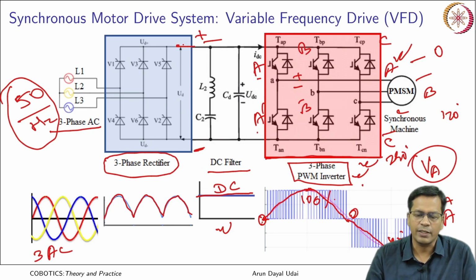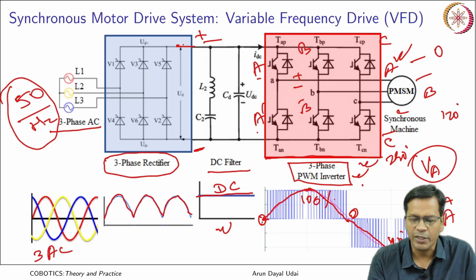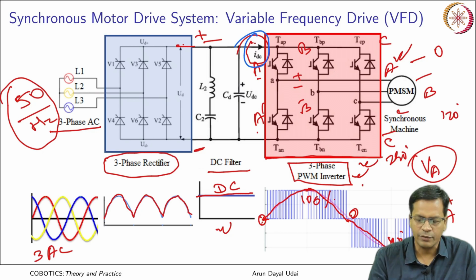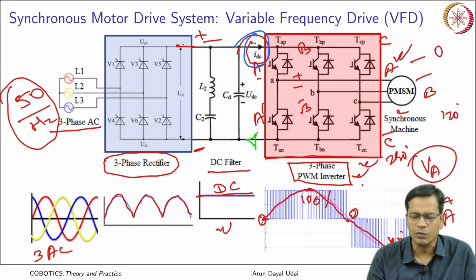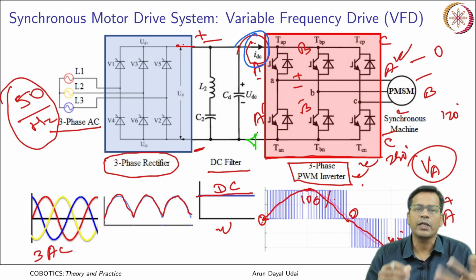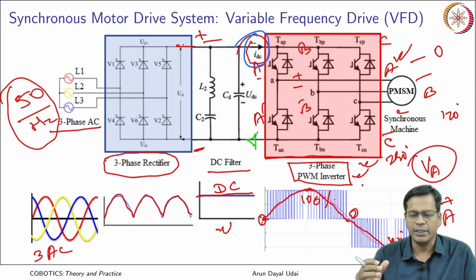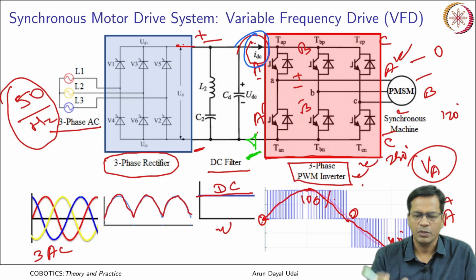Okay. Now, if you can control the current that effectively goes here, let me use a different color. So, this is it. If you can control the current which is actually flowing through this wire, then you can control the torque as well. So, there is a DC chopper drive, again a chopper drive which is here, that can control the torque of this PMSM machine. So, you can have a similar type of chopper drive which can control the torque.